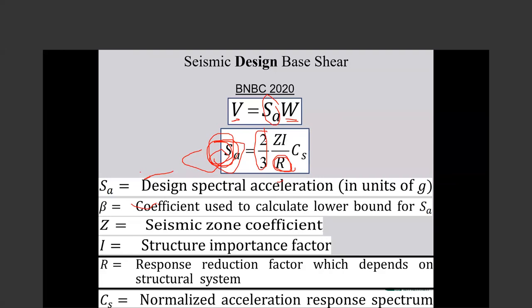You know that the design level earthquake will impose R times this value to the building. But we design the strength, ordinary strength design, for 1/4 of that load. So we accept damage. We, as a designer, are making damage to this building at the design level because we divided by R.